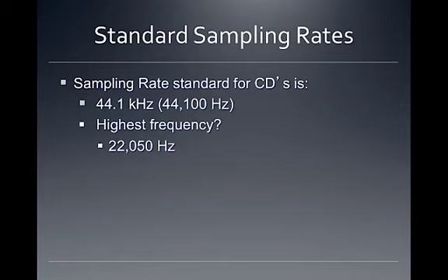Well, when those samples are taken at a lower sampling rate, so if we're only sampling at the ability to record 20K, but the A to D converter is hearing 24K, then we have problems, and it's called aliasing, where we actually end up hearing sounds within our frequency spectrum that are not the real sounds. They're aliases, but they are in fact sounds that we can hear, and that to us is bad.